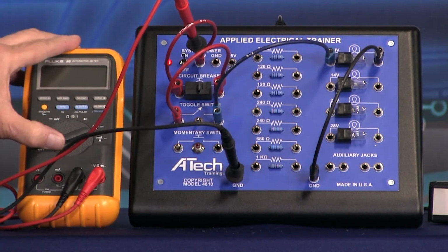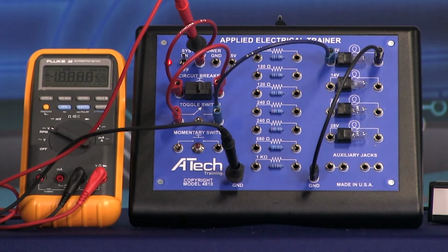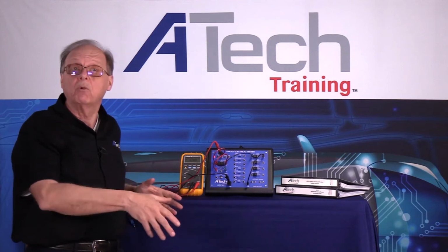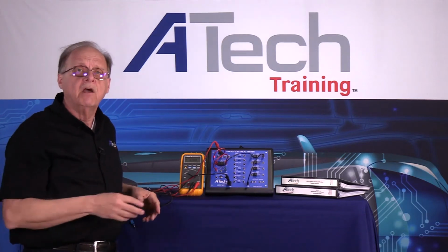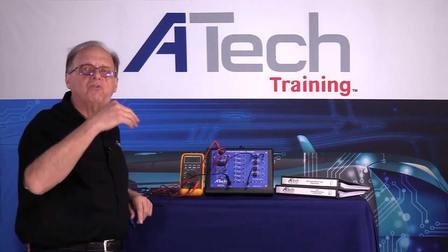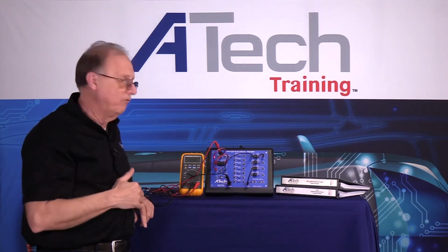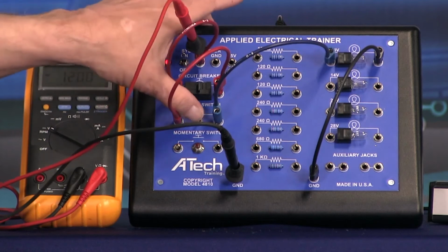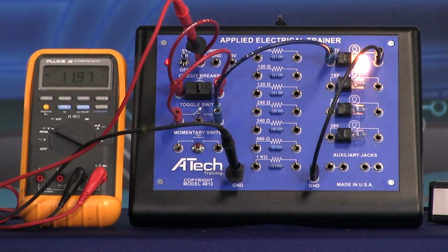I'm going to turn my voltmeter on, and if you'll notice, I got 12 volts. This would be the open circuit voltage at the battery being fed into the circuit. Now, if you read 12 volts throughout the circuit, that circuit's open, because the voltage should drop as you use some electricity. So if I turn this on, notice I went to 11.97 volts, and notice my light's on. So I'm actually feeding voltage into the circuit.